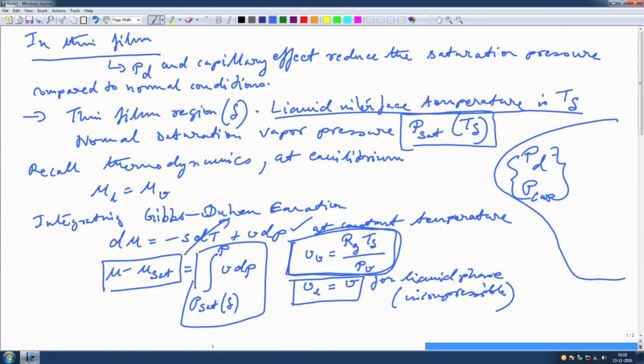And these are very important in many applications, especially for thin film dynamics. When you do materials processing, for example polymers, thin polymer films, the disjoining pressure plays a large role. We have not gone into the intermolecular perspective except giving an idea that this is governed by the Lennard-Jones 6-12 potential, or you can adapt a form like that.